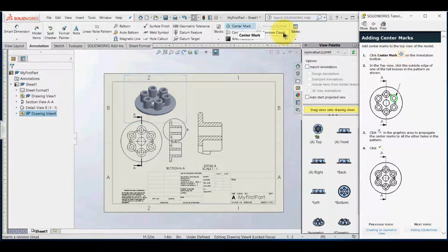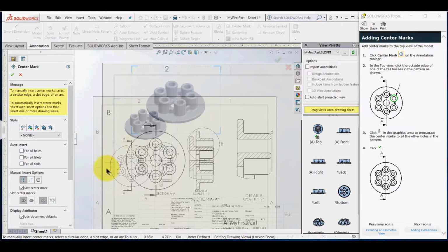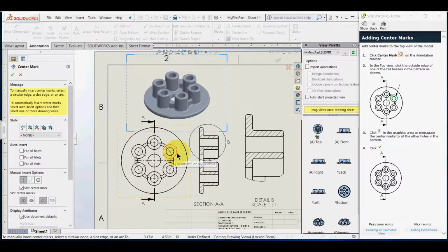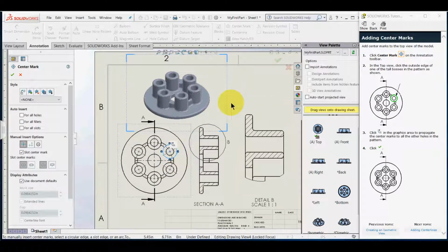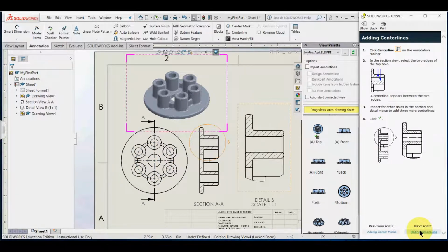So now we're going to put that center mark. We turned it off, but we're going to go ahead and manually dimension it. So click the center mark, and then select the outside circles here, and it should do them all at once because we've joined them. So we'll select the outside circle, either one actually, inside of the outside. You can see it's already done here, so we're in good shape. And then when we clicked, it rotated around, so we're showing that it's centered.